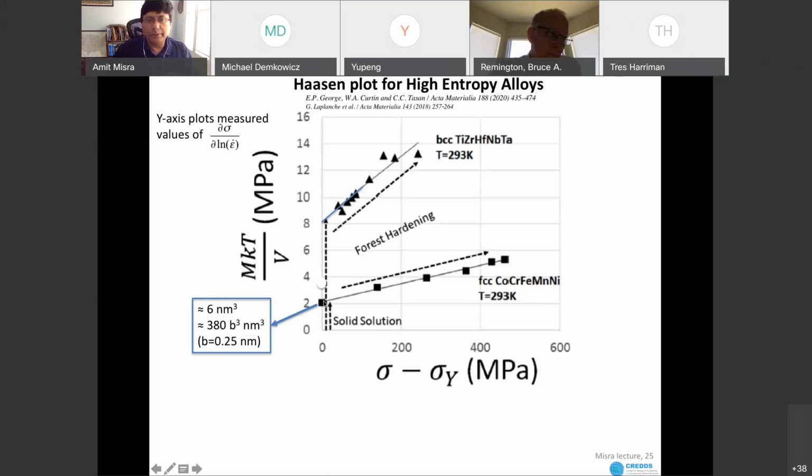There are different definitions of yield stress, generally by some offset value, about say 0.1 or 0.2% offset plastic strain, which is defined as the onset of plastic deformation. Some of that, I guess, is the definition of what you would call yield strength. This is the stress at which you start to measure a permanent strain in the material.